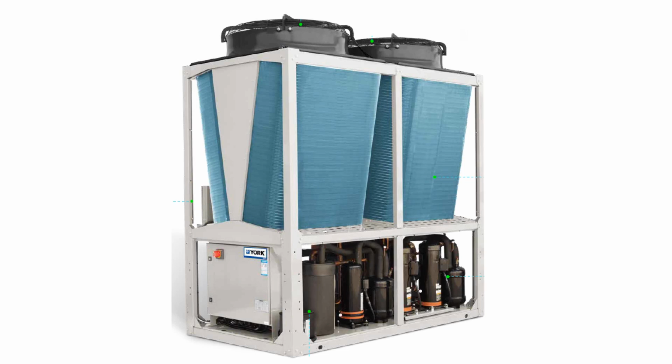Per the project requirements, the system is meant to serve the building for its life of 30 years. The only equipment that will make a 30-year lifetime would be the water-to-air chiller, whereas the other 2 have a lower lifespan and would have to be replaced at least once within the building's 30-year life.